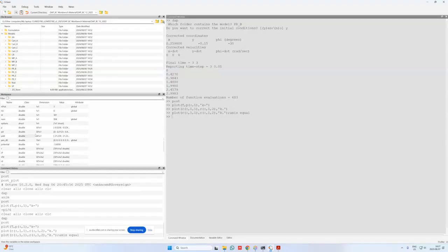Right, so now jumping into the reaction forces, which are associated with the Lagrange multipliers. I see that the form of the Lagrange multipliers is 301 by 2. This makes sense in the sense that I have 2 constraints that I specify based on the revolute joint. The revolute joint limits motion in the X and Y directions. So 301 by 1 will refer to the X reaction forces, 301 by 2 will refer to the Y reaction forces.